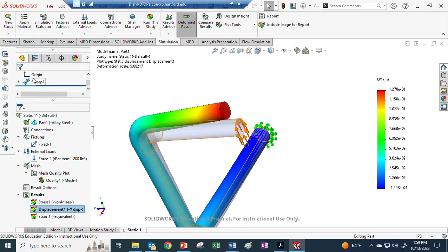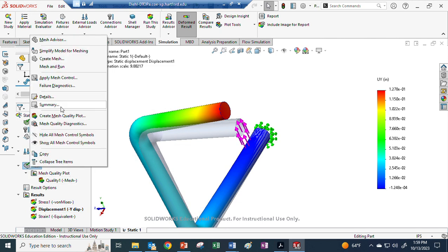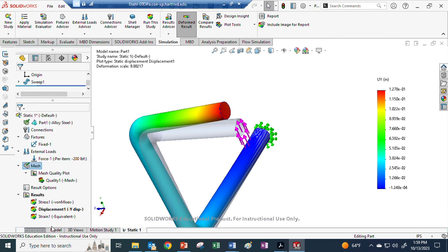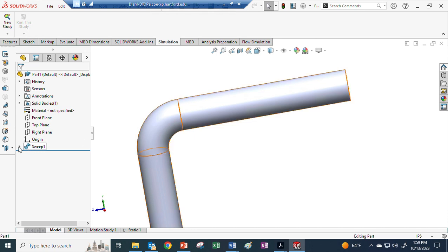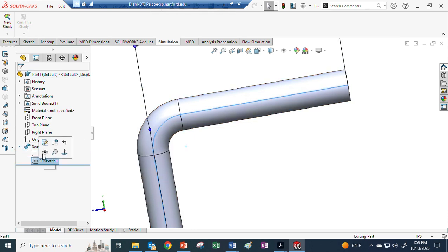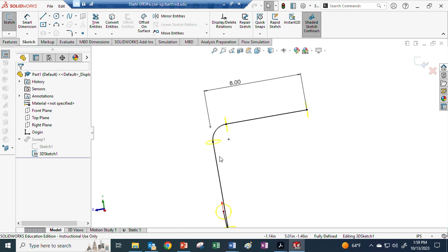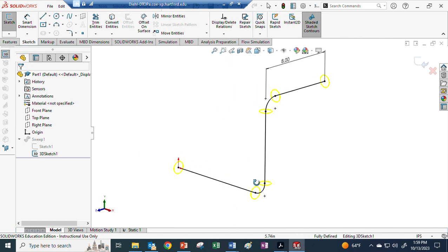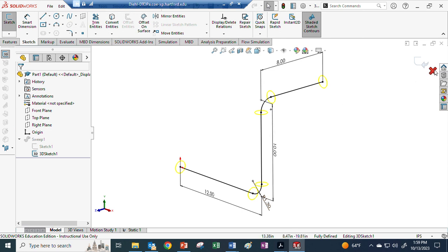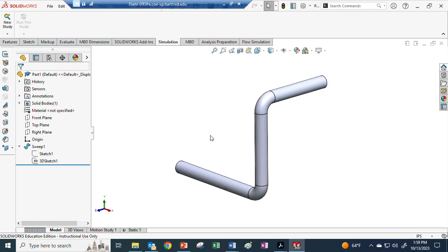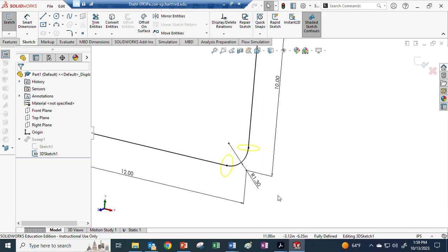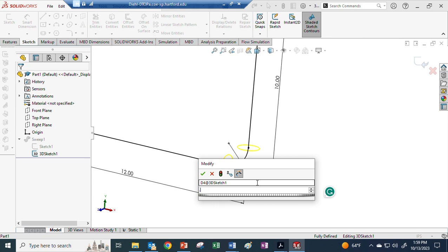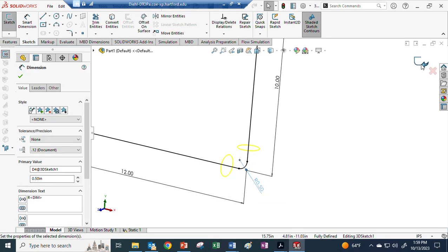0.253. So a couple of things we might want to do is remesh it. Well, actually, in our model, those fillet radii look like way more than I intended them to be. So I can go to here, and I think it will let me. Will it let me? It's not letting me. Can't I just? Oh, there it is. Okay. What if I go down to 0.5? Will it allow it to be built?